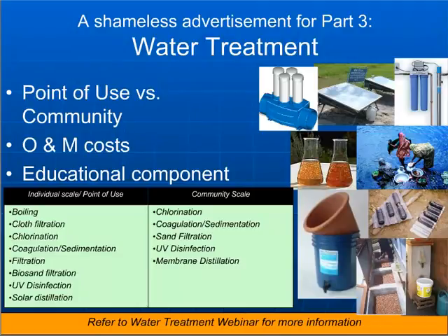So I mentioned at the beginning, here's a list of references and resources. A few of these that I would point out are, of course, the EWB guidelines for water quality and water resources. The other one here is the Handbook of Gravity Flow Water Systems by Thomas Jordan. This one goes back to probably the late 60s, early 70s, but it's still a very, very valuable reference book for people designing these water distribution systems in developing countries.